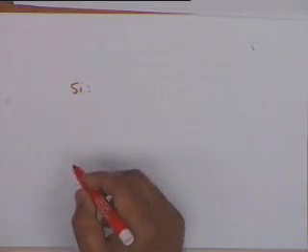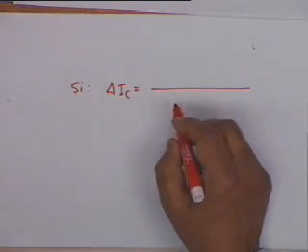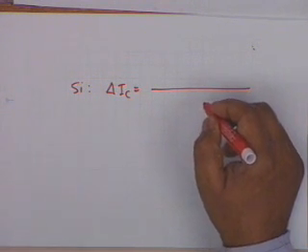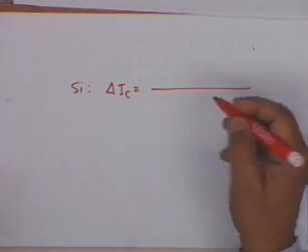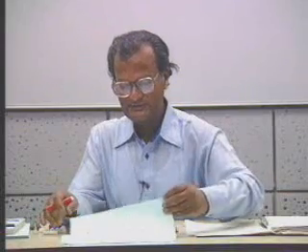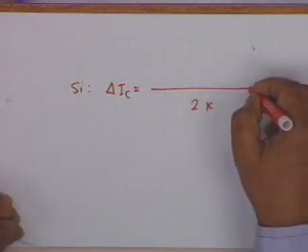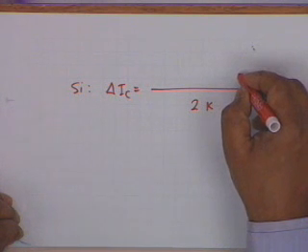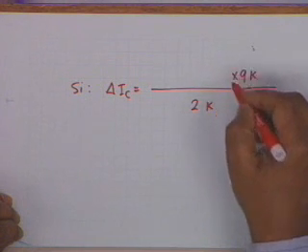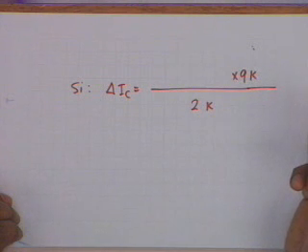So if I take silicon, delta I sub C shall be equal to, let us take some specific values of RE, or let us take for the same design, the design that we had just, let us take 2 kilo, okay, 2K, and what did we take RB? 9K, alright. Then delta ICBO for silicon would be 31 times 10 to the minus 9,